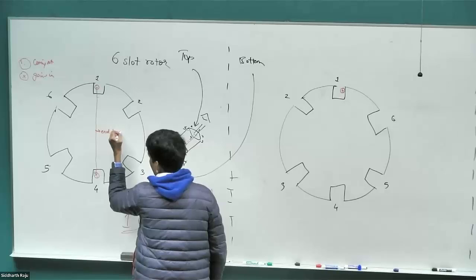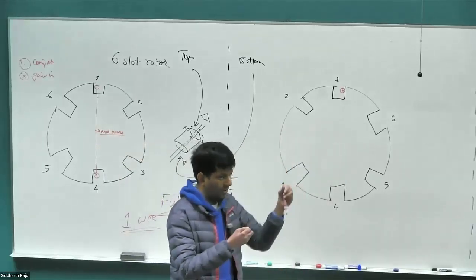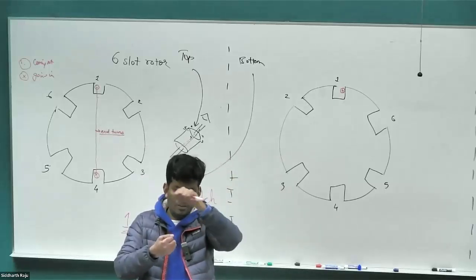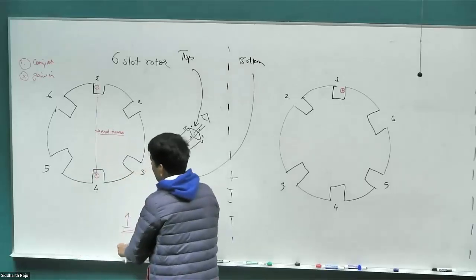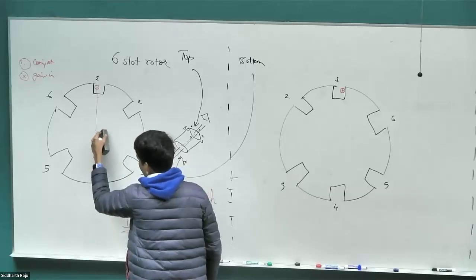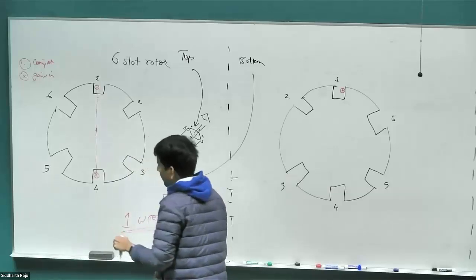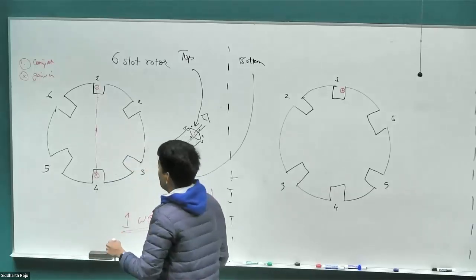End turns. Right? It happens on the top, and similarly when we do the bottom, there is a bunch of end turns. So when you saw the rotor structure last class, you'd have seen a whole bunch of conductors on the top. Those are quite useless to produce torque, and they do create quite a bit of leakage inductance, which has a negative effect on the motor operation. But in our case, we're looking at a very ideal, simple case, so we're not going to worry about it. But these windings are called the end turns, which are useless for torque production.